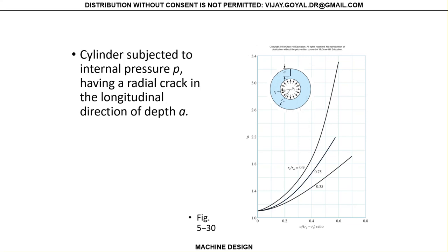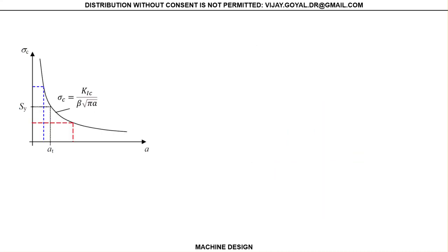Okay, so to better understand this, now there is a criterion by which we can determine, if there is a crack in the structure, whether it is going to fail due to yield, or is it going to fail due to fracture, crack propagation. So we have a nice criterion that helps us do that. We got something we call the transition length.